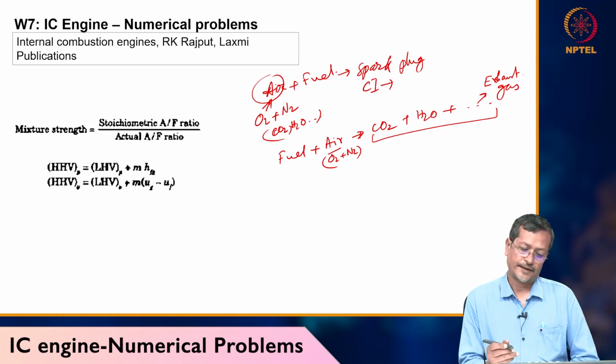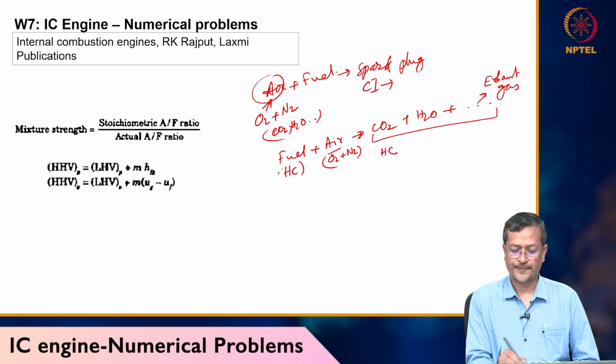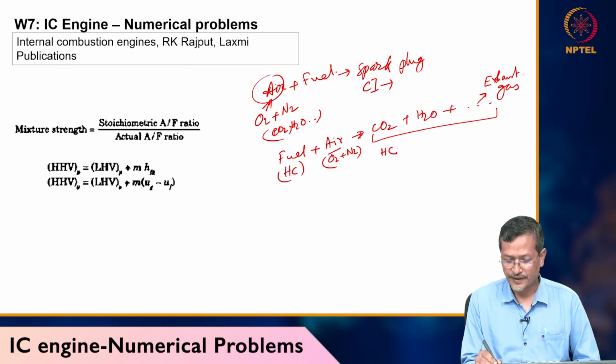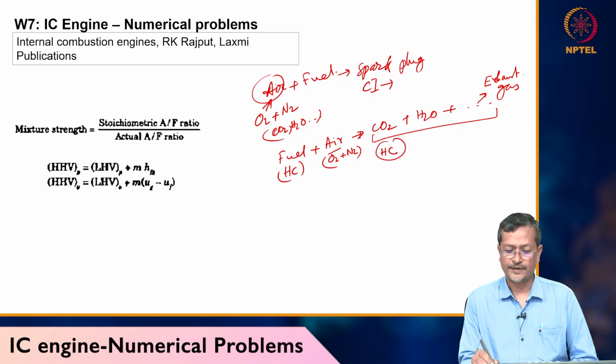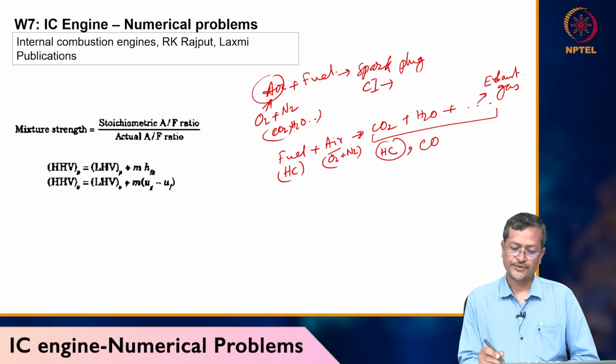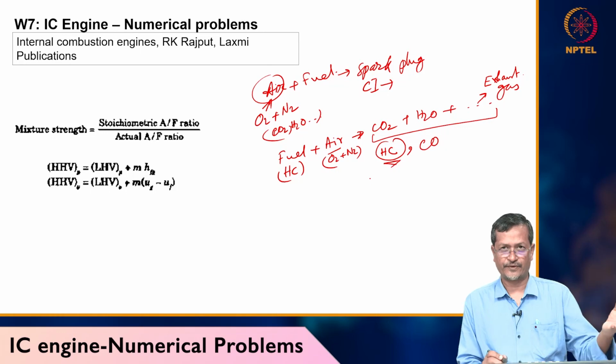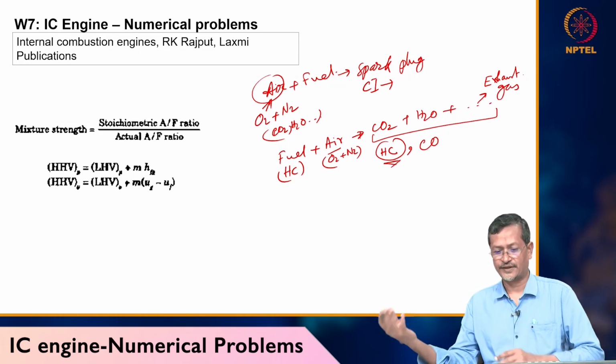So, actually it is not giving any energy, rather it is taking away your heat. And if you have less air, what will happen? In that case, hydrocarbon, meaning fuel, will be in your product, or maybe carbon monoxide. Hydrocarbon means your fuel is not burned completely, so you are not getting the complete value for your money. Whatever you invested in fuel is not burning, so you are not getting all the energy.